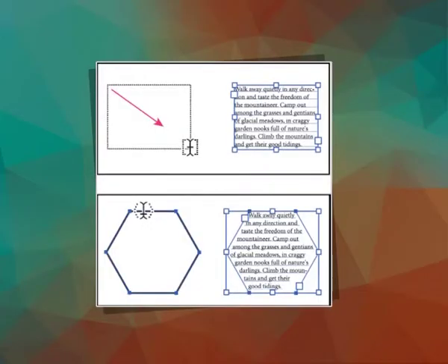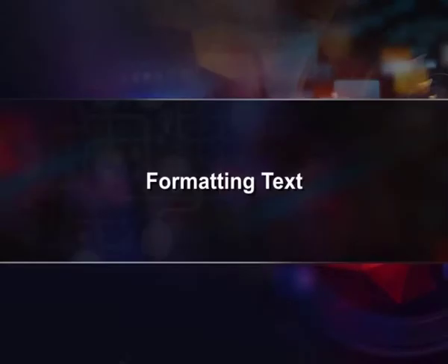Enter text in an area. Area type, also called paragraph type, uses the boundaries of an object to control the flow of characters, either horizontally or vertically. When the text reaches a boundary, it automatically wraps to fit inside the defined area. Entering text this way is useful when you want to create one or more paragraphs, such as for a brochure.